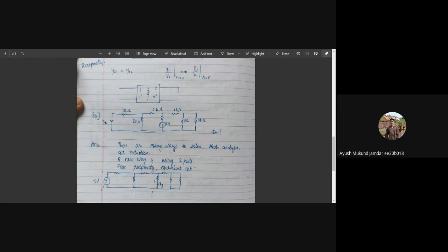This can be applied in this circuit, and since the ratios will be the same, that is Ix by 5, using the theorem I can replace the 5-volt source by a wire with a current Iy flowing through it, and on the second port I can have the 5-volt source, again any source.